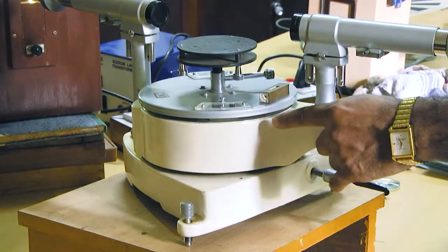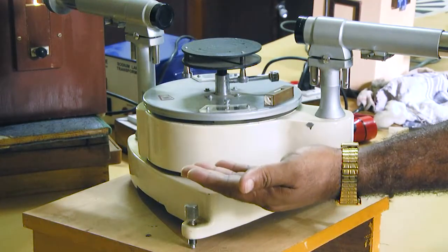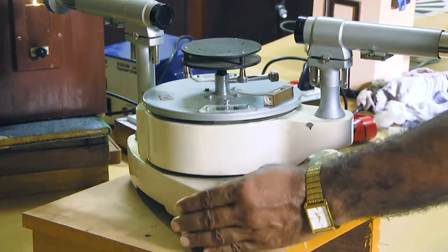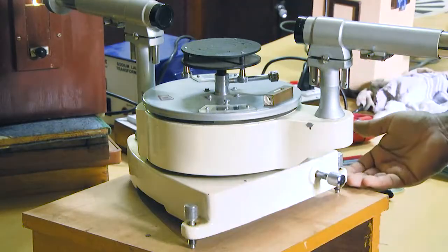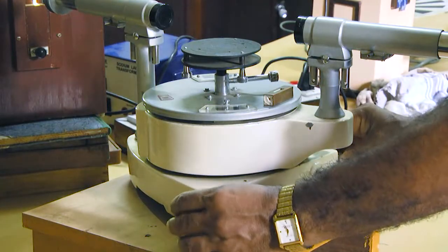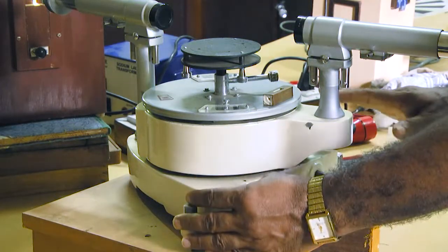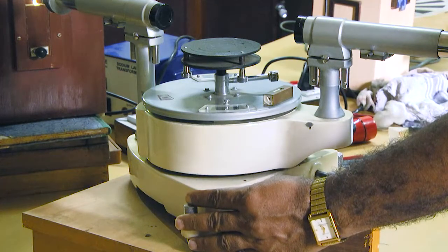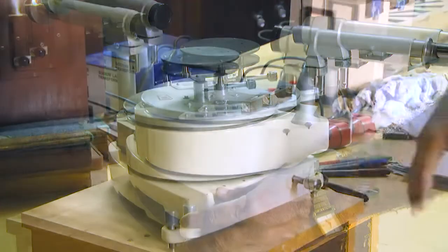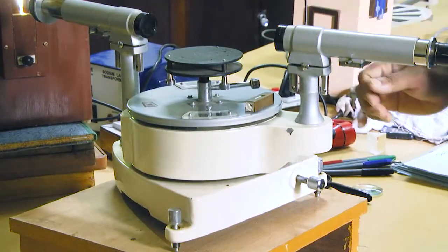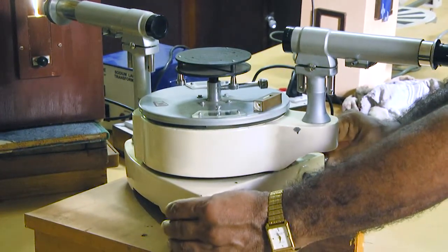Because you are rotating this one, say, to make the height higher, that means the same effect you will get if you rotate the other one and take it down. So, that is why at a time we rotate in opposite directions, so that this will raise the height and this side will get down. Your purpose is to make it horizontal. To get this horizontal position, we just rotate this screw in the opposite direction.